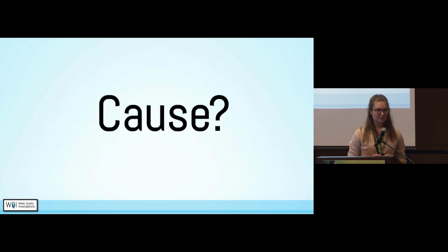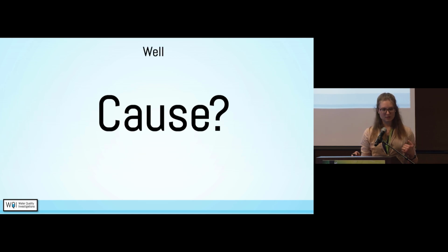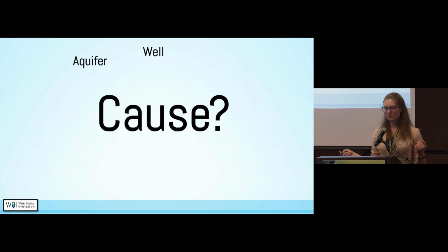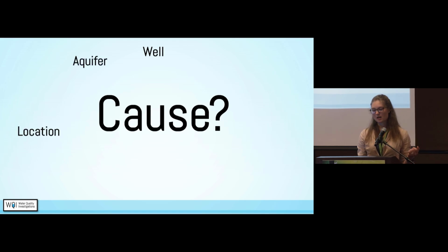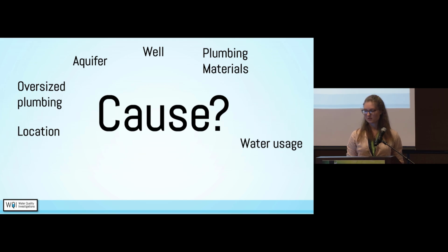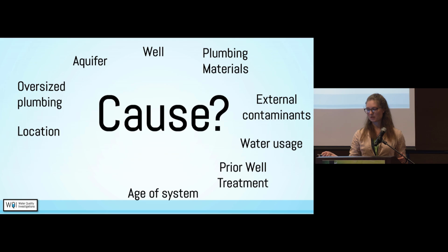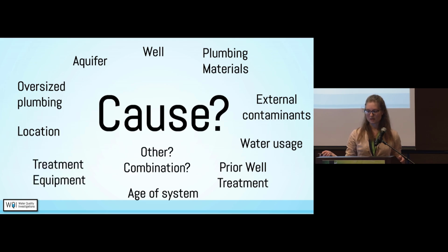It's really difficult to figure out the cause of what a biofilm issue is. We're working with a lot of different factors, such as the well, we've got the aquifer, we've got the location, and that would also include geology, plumbing materials, oversized plumbing, water usage, age of system, external contaminants, prior well treatments, treatment equipment, others and combinations of these things.